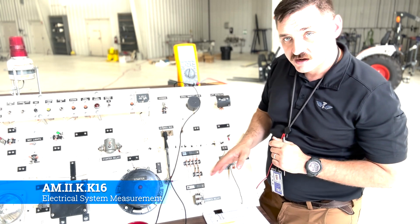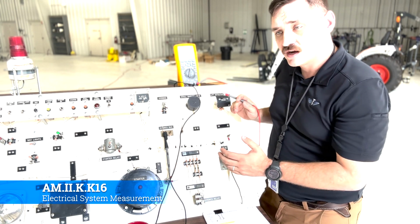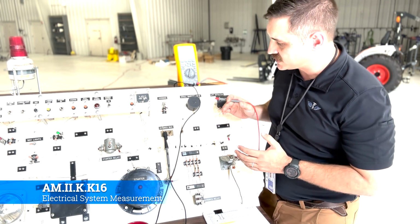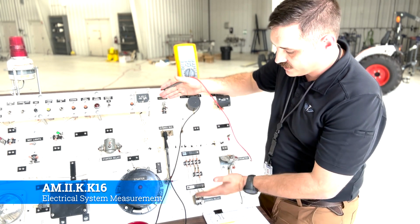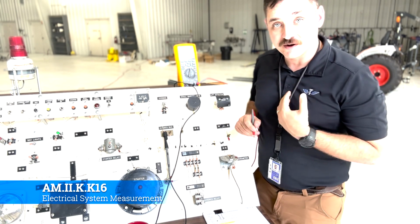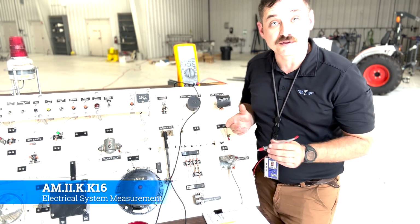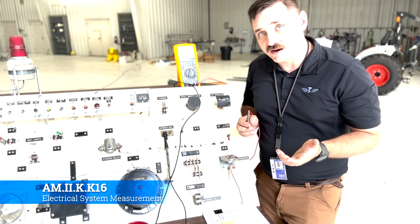So if the relay works, and then we know that the rest of the avionics systems work, then we can pretty well deduce that somewhere between here and here is the problem. The question is where. Now, I happen to know that there is a disruptor circuit right there that the switch is turned off right now. That's why the light's not coming on. But we wouldn't know that on an aircraft.